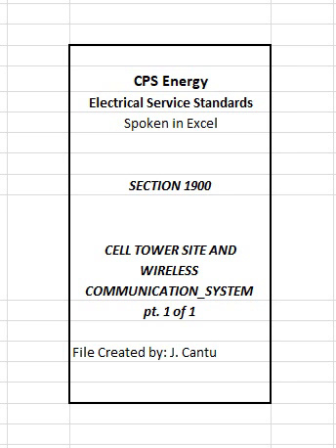C. Underground service on customer meter pole. Service and metering equipment shall be designed to be installed on customer's meter pole along with necessary communications equipment. Customer meter pole shall be located at an approved location on customer property or a pre-approved location on public right-of-way, refer to figure 1905.